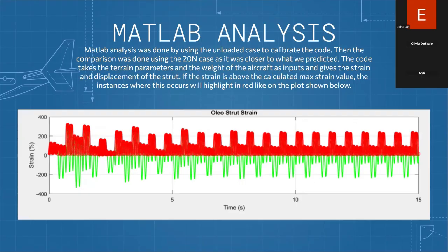The no loading case was used to calibrate the damping constant, and the forces that we got from the Blue Hill load frame system were averaged and used to find a spring constant. The system was then run with the 20 Newton weight, as a 35 Newton weight had significantly more inconsistent force values, but that was to be expected given that it was pushing the shaker table towards its limit.